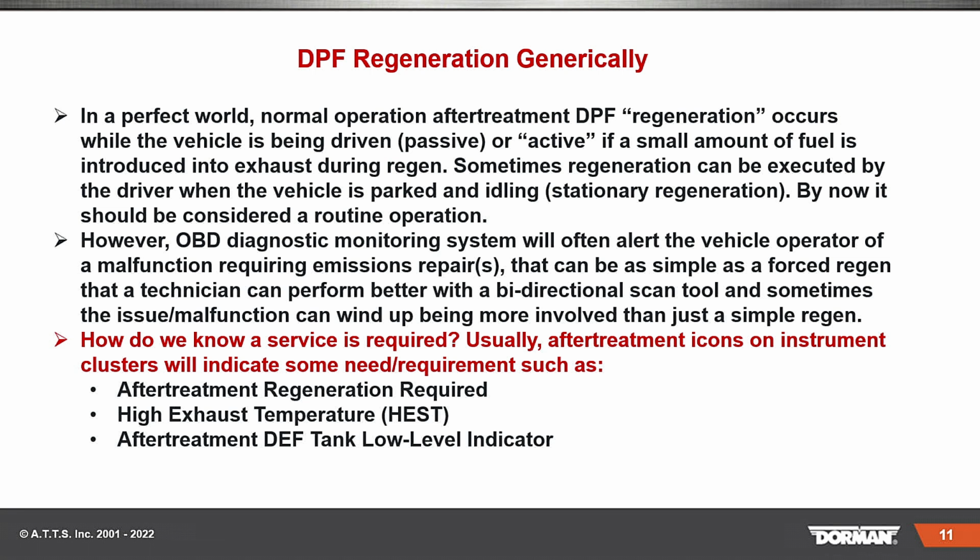Now, however, the OBD diagnostic monitoring system will often alert, and that was a nice thing with the OBD, okay? It will often alert the vehicle operator of a malfunction requiring emissions repairs that can be as simple as a forced regen, that a technician can perform better with a bidirectional scan tool. Sometimes the malfunction can wind up being more involved than just a simple regen. Because don't forget, these things need heat, they need to run. We have vocations out there, buses or whatever, stop, go, stop, go, stop, go. They never get hot enough, so they need a little bit of an interaction, okay?